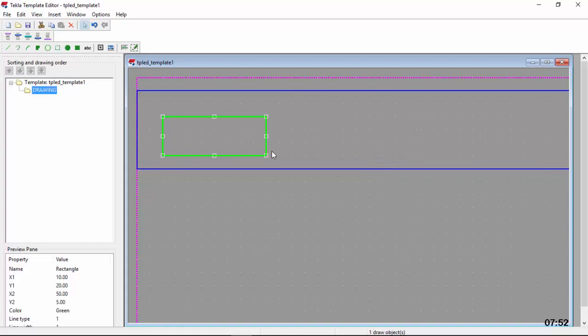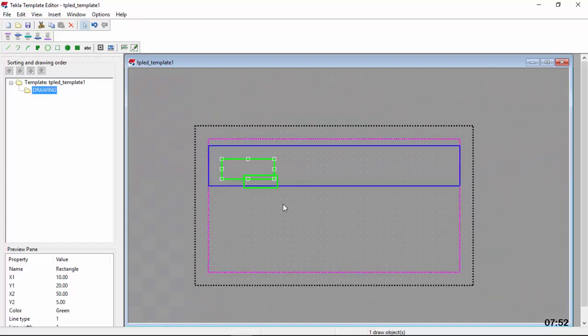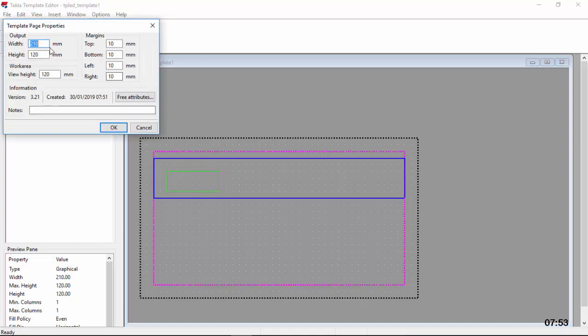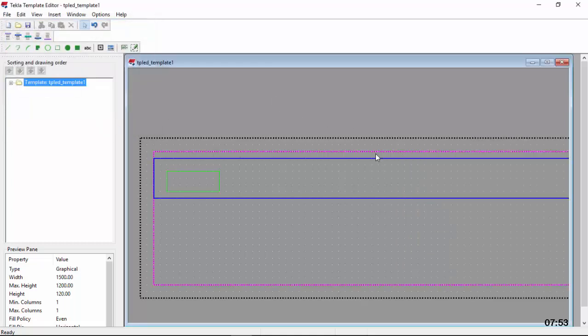I'll click on stretch outside, and I want to extend the boundary of my title block. I want to make it larger, this blue rectangular. To extend it, I'll just double click outside it and come to this and just feed whatever dimension there, as long as my title block will be able to move in freely. Now I'll just type there 1200 and I click OK.